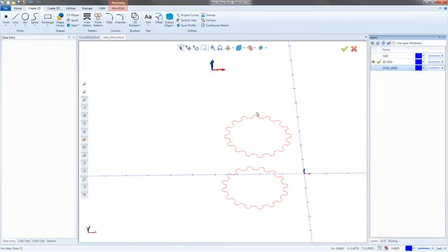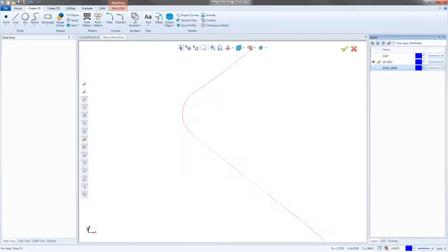So if I zoomed in and it stopped over here and my chain was red and then it went back to blue, you'd zoom in on the area where you had the red chain meet the blue. And a lot of times you'll either see that you have an overhang, a gap in the geometry. Sometimes it happens with solid models. When you pull it off, a solid model might look really clean when it's made, but as soon as you start pulling geometry like lines off, you might see that it doesn't mate properly and it just doesn't clean up. So you'll be able to clean it up.